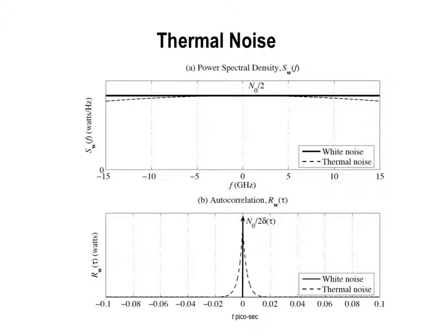There remains one property that we need to describe. So now we have described the power spectral density, the autocorrelation, and the time variation of noise. What else? It's random. So what do we need to describe for a random variable? It's the probability density function. So noise as a value is Gaussian distributed. The PDF of noise takes a Gaussian distribution. Why?